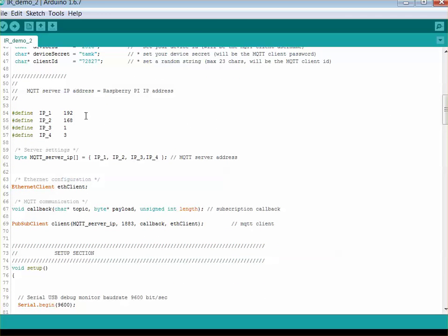And this is a really important part here. The Arduino will get the IP number from the Ethernet system, but what has to be fixed is the Raspberry Pi's IP number. So in here you have to dig out what your Raspberry Pi's IP number is. The system is not working if the numbers are not correct here, but that you have to find out from the Raspberry side.